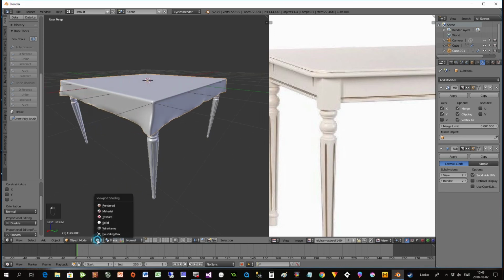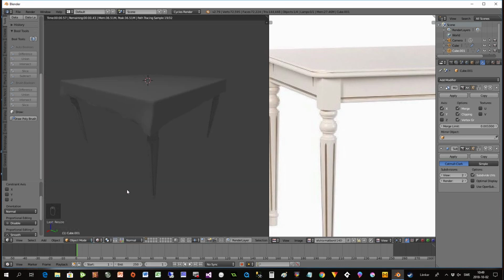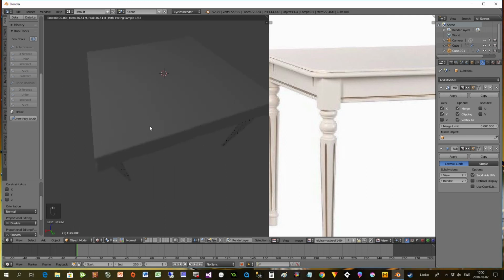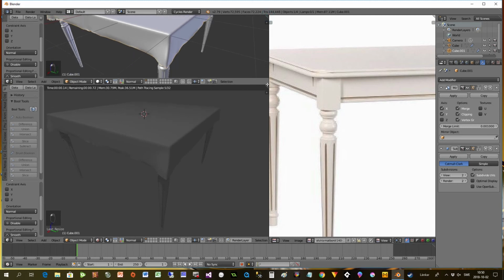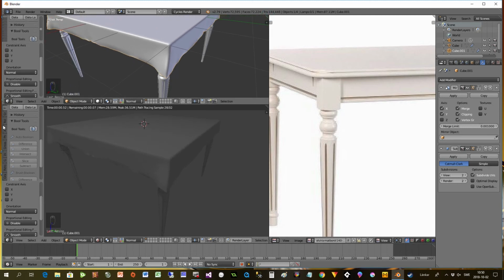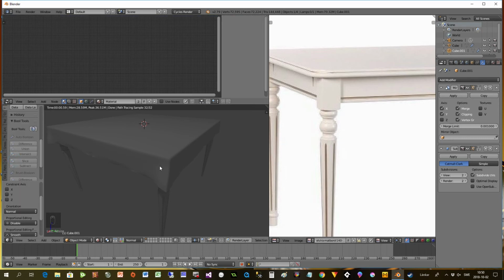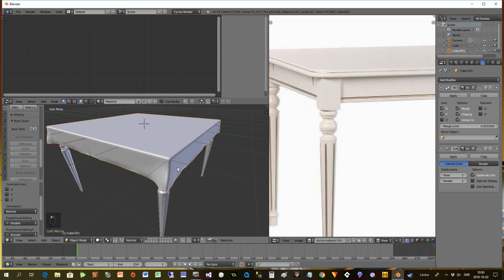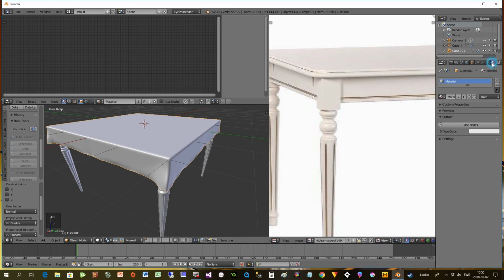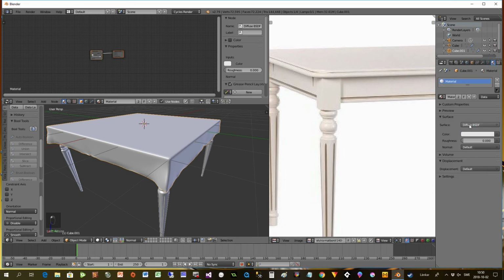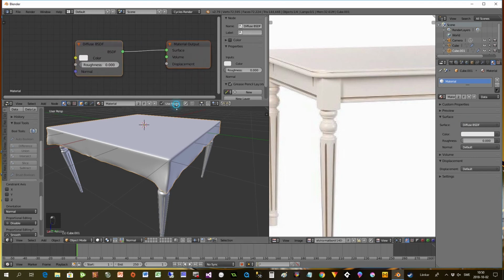And if we press render now, it will not have any good patterns at all, but it will have some cloth here. So to make that, you just do like this. You go down here, you select node editor, you go to solid so we can see, you have this selected, you go here, you select use nodes, and now we should do some magic.